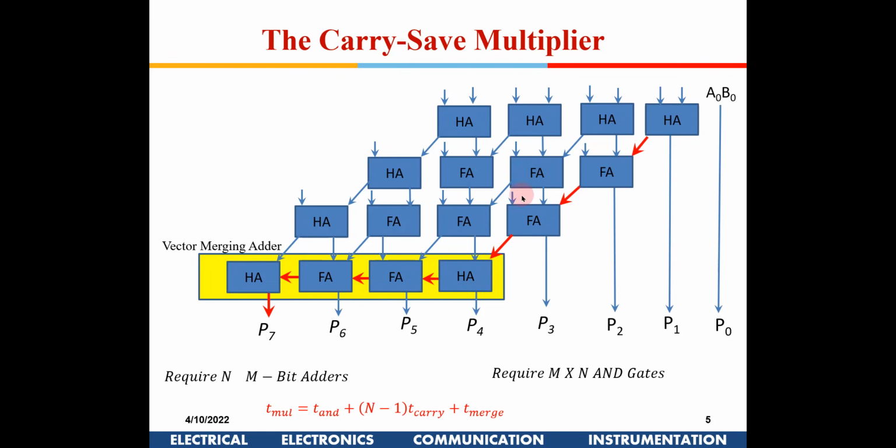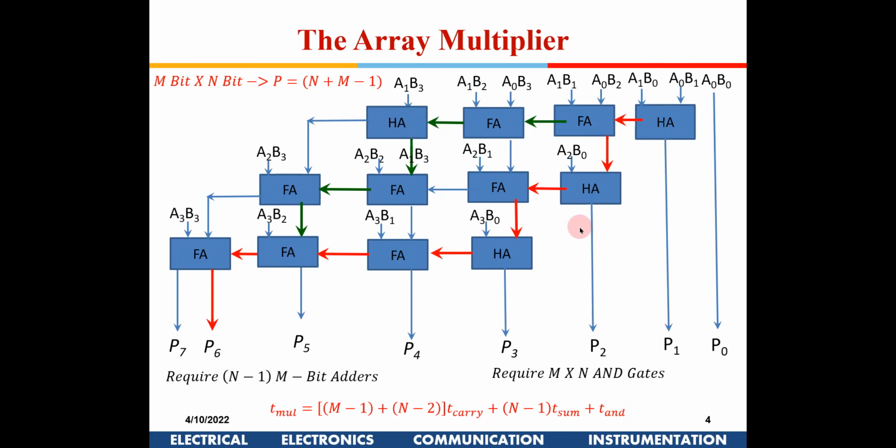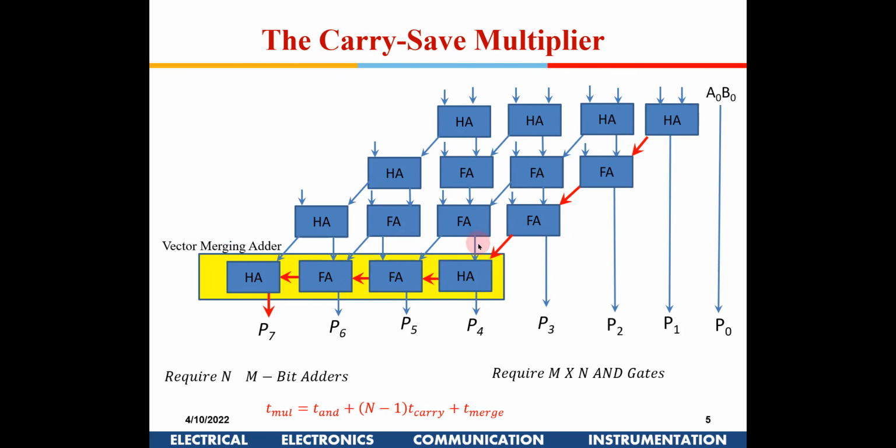Here we are talking in terms of just a 4-bit into 4-bit adder. If you are thinking of an 8-bit into 8-bit, you can think the critical path will be only in the corners, and for the rest of the whole setup, we don't have to bother about optimizing the size. So the savings will be much more.